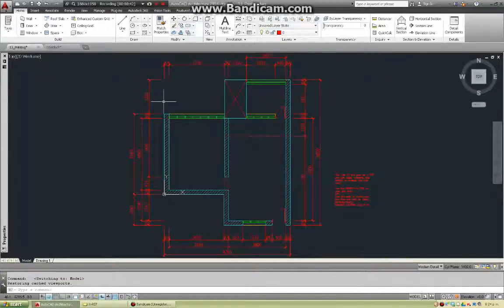So in AutoCAD, there are two main areas: the paper space and the model space. Over here, we're in the model space, and we know because this tab is checked. In the model space, that's where you're going to do all your drawings, your actual lines. And the paper space, which is the next tab over, I think they also call it the layout tab, but I've actually renamed it to drawing number 1.